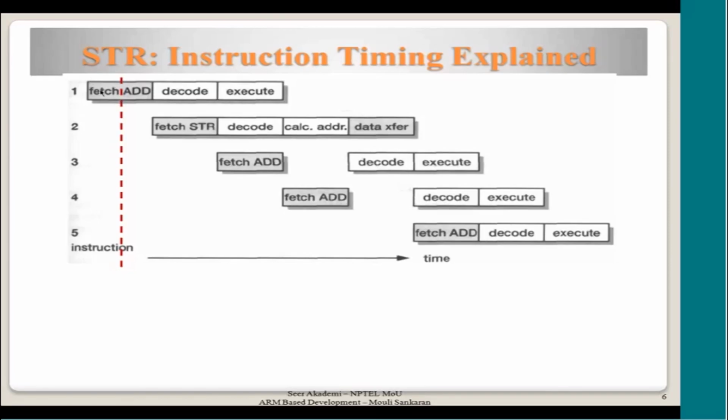I didn't show you what is prior to this. So in this case, we don't know whether this particular instruction is being fetched for the first time, with maybe a data transfer prior to this. That means the first cycle would have been a non-sequential cycle. So the possibility is that it could be a sequential cycle or a non-sequential cycle, because you don't know what has happened prior to this cycle, as that is not shown here. So we can't make any guesses on how much time it has taken.